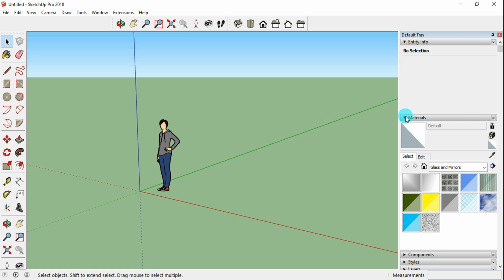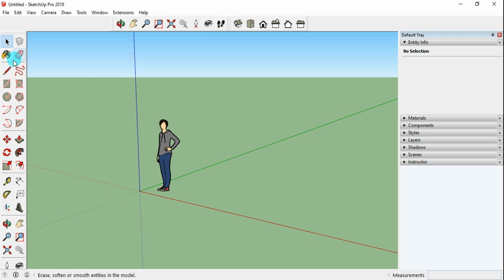Okay. And similar way, while drawing anything on the screen, for example, I just want to draw a line here. And if you want to give the measurements for this, how can we define the measurements? So just have a look at right side, right bottom. You can see some measurements here, like 17 feet 3, 1 by 2, okay. So if I want to draw a line of 10 feet, so simply define the value, just type the exact value you need there, okay. So according to the template or according to the unit setup given there, okay. So since this template is in feet and inches, I've taken 10 feet there, and just after giving the value, click on enter, and you are going to get the line like this, okay.